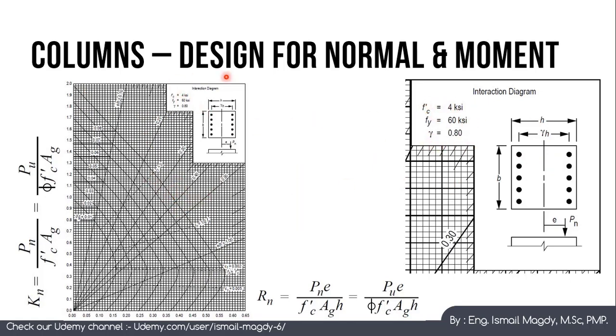Here, these are the main data of this interaction diagram. There is a different interaction diagram for each f'c and fy, and also for each gamma, which is the ratio between the dimension between the reinforcement on both sides of the column and the total width of the column. So this is the width minus the cover from each side, and this is the total width of the column. For example, this interaction diagram is for gamma equals 0.8, fy 60 ksi, and f'c 4 ksi.